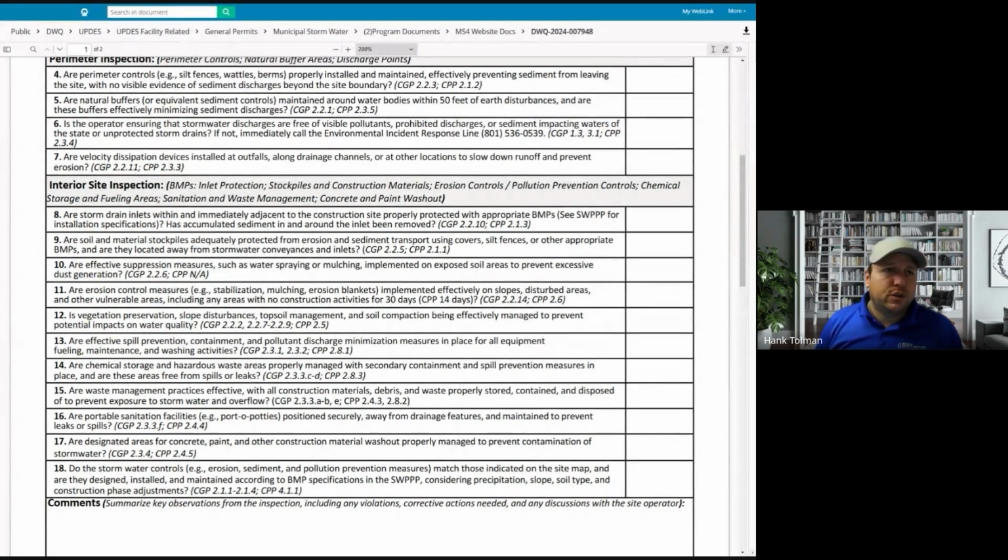So it used to be that we would just say, you know what, we're going to grade this whole thing out. It's just not feasible for us to wait and grade it out later. Now what they're saying is feasibility means that it could cause pollution to groundwater if we leave that topsoil or that vegetation there, and channel that water to that vegetated area. So we got to take a stronger look at that. And a lot of the municipalities are going to be looking at areas that could be preserved vegetation instead of just clearing and grading the entire site.